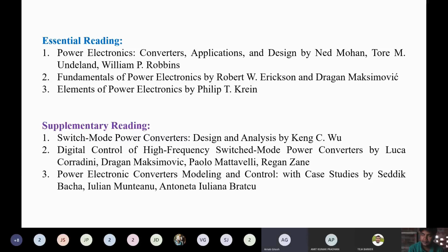In our courses, we are also using a lot of transducers, like voltage transducer and current transducer. For voltage we can use LEM. LEM transducers we are using, like LV 25-P and LA 55-P. Different transducers we are using for the voltage as well as the current. So LEM means it's a Hall effect transducer.